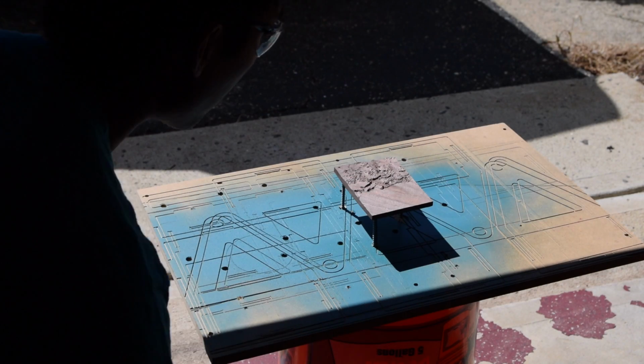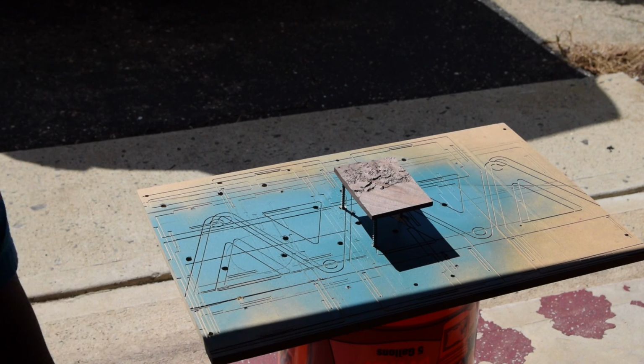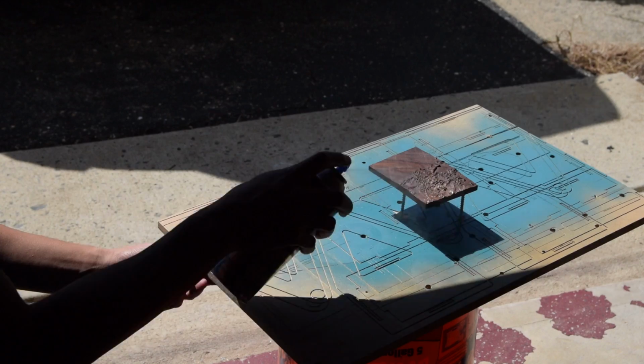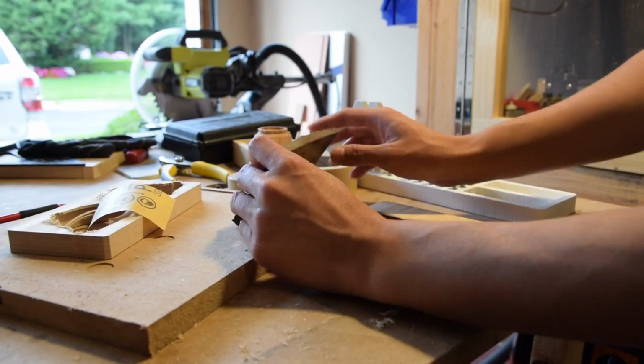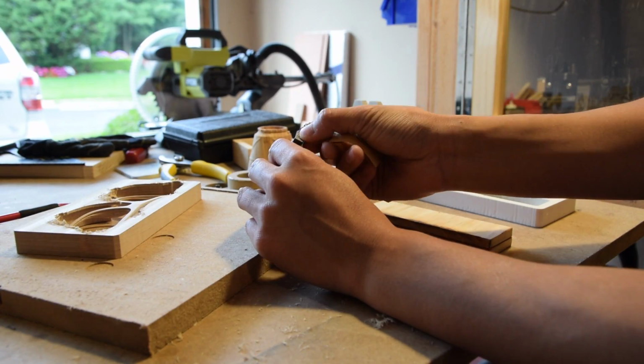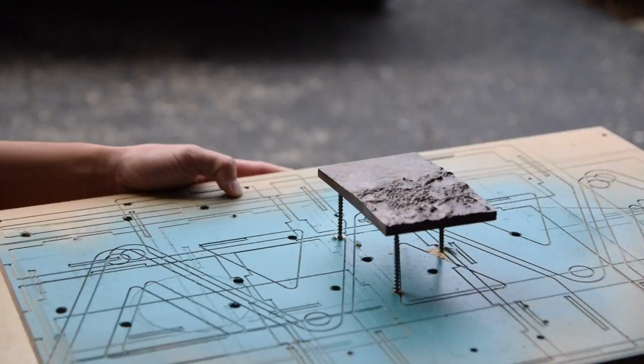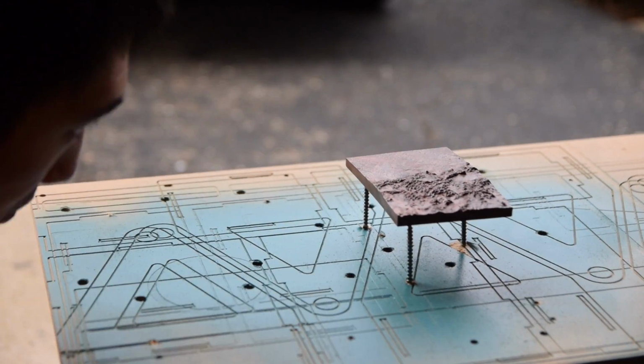To coat both the front and the back in the same day, I drove screws through some scrap MDF and used them as standoffs. After a day or two, I came back and buffed the edges with some fine grit sandpaper to knock down the grain where it had been raised. I gave it one last coat of polyurethane to reset the surface texture.